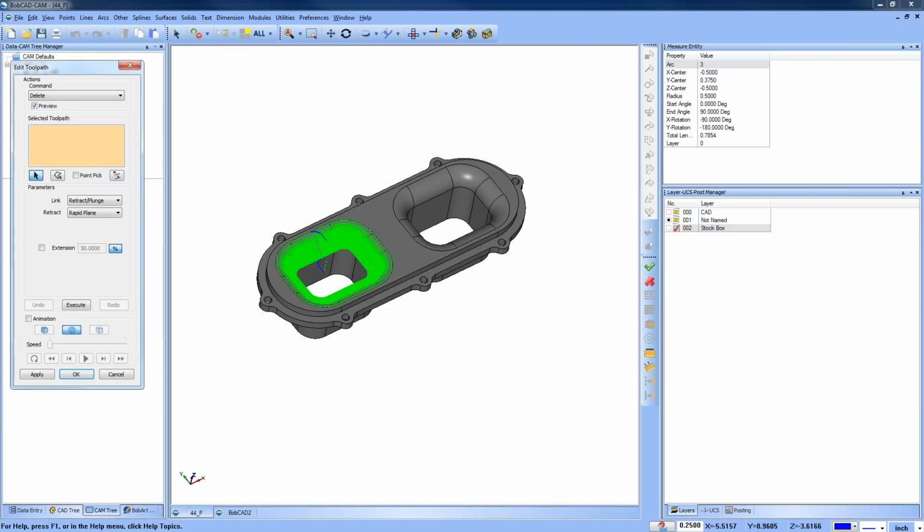Mike says, I have been using lathe today and the simulation has X and Z axis reversed. How do I reset this to match the drawing? Mike, the display of the software is less important than the posted code. I would post your code and make sure your X and Z is set up correct.